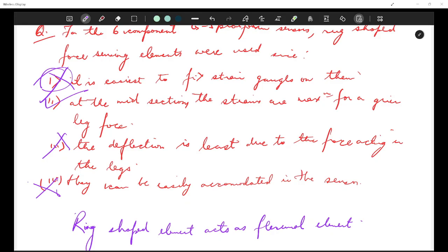"They can withstand more loading." Flexural joints usually withstand less load than rigid mechanical joints, hence this is wrong. They are chosen for precision and not strength.